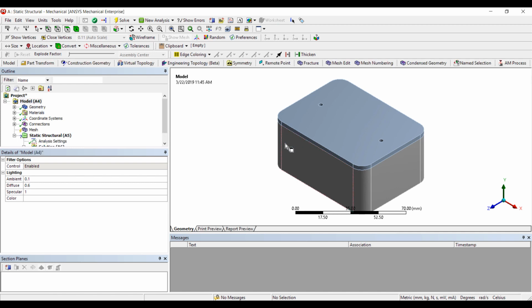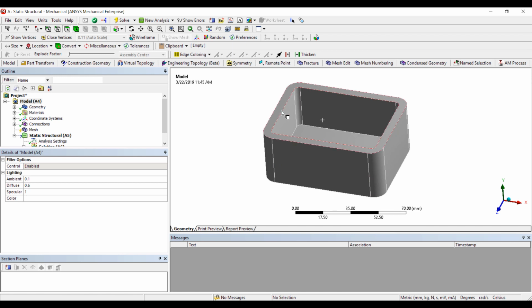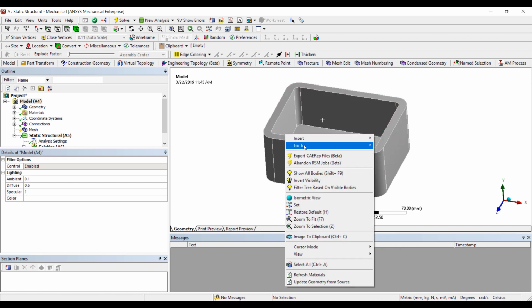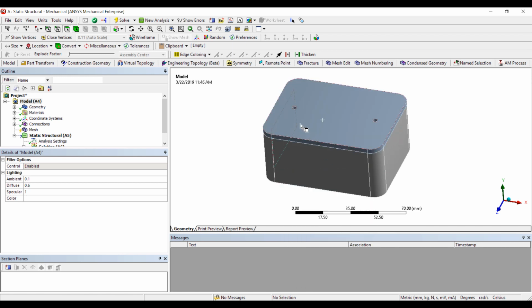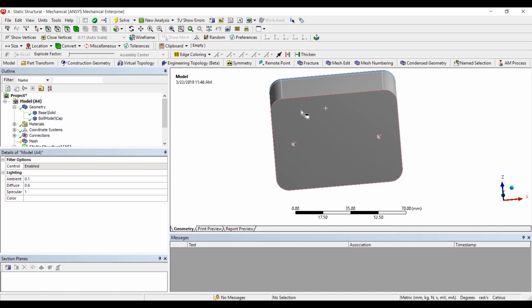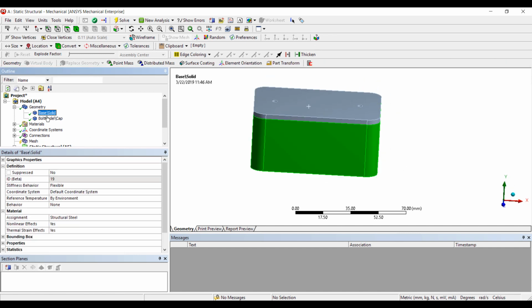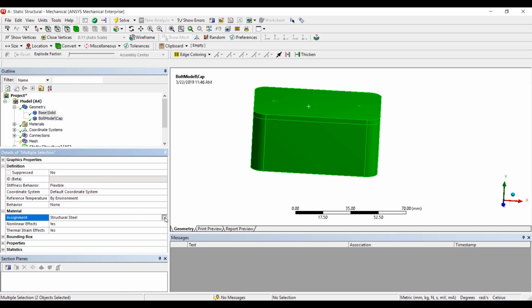So it's a simple geometry. It's not a well-designed box. As you can see, it's just flat. The lid just lays flat on the box itself. I left a couple of holes for bolt pretension, where the bolts will go through to pull the lid and affix it to the base. So both parts will be made of polyethylene, and we'll assume the bolt is made of steel.